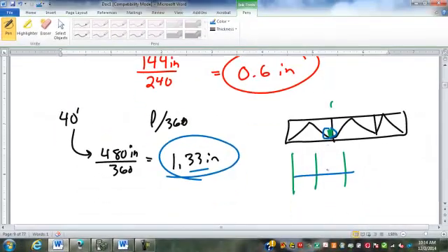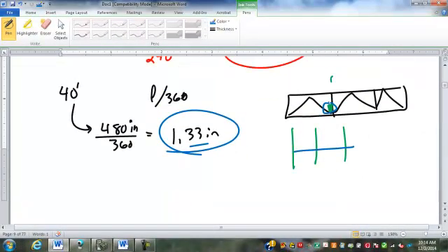The other thing those strong backs also prevent is sideways buckling on your beams. It's possible for the beam to twist because it gets under so much load. It doesn't fail in bending, but it starts to twist a little bit, and that prevents that as well. If you've ever seen a floor joist that has done that, especially if there's a finished basement underneath, it makes a mess. It rips the sheetrock, really rips slots in the sheetrock. It's horrible. So anyway,